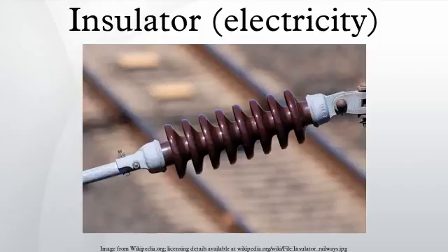However, wires that touch each other produce cross-connections, short circuits, and fire hazards. In coaxial cable, the center conductor must be supported exactly in the middle of the hollow shield in order to prevent electromagnetic wave reflections. Finally, wires that expose voltages higher than 60 V can cause human shock and electrocution hazards. Insulating coatings help to prevent all of these problems.